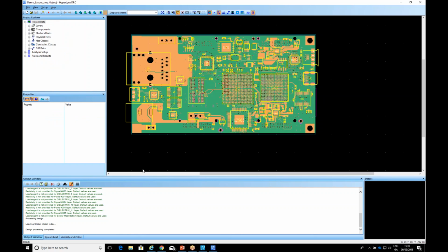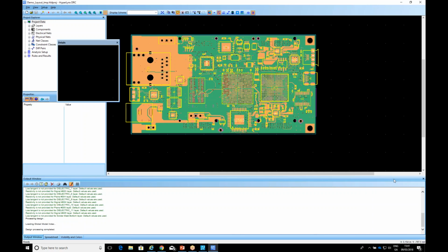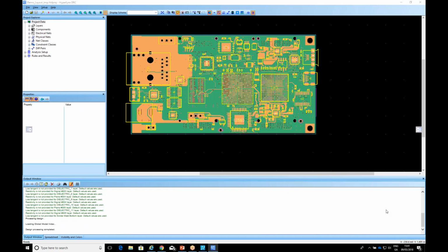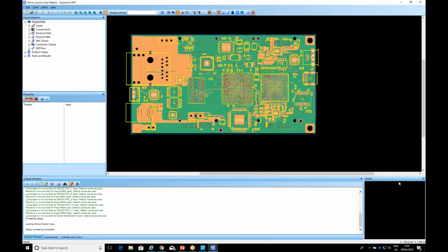And really the first window that you're presented with, within this number of windows, you've got the capability not only to set up the project, you can also verify the design that has been imported. You can configure some rules, then run those rules, and then interpret any rule violations. And again, with any of these tools, if you don't like the way it's set up, you can change the window locations or move things around the way you want them. Just double click on the banner of that window, and it will free it up, and then you can place that wherever you'd like to put it.